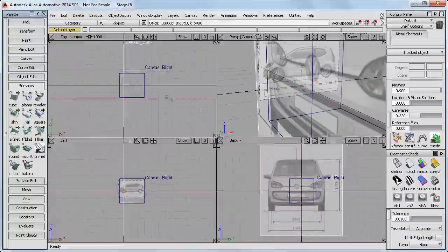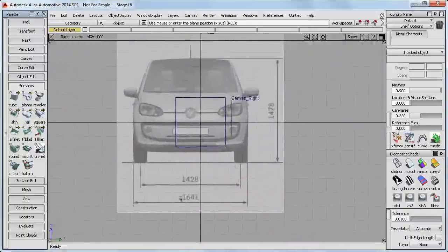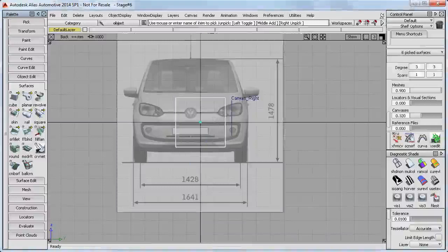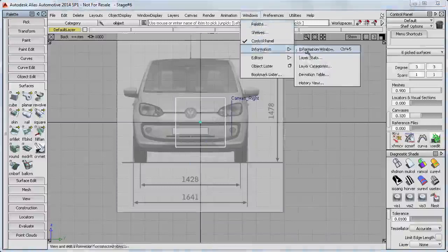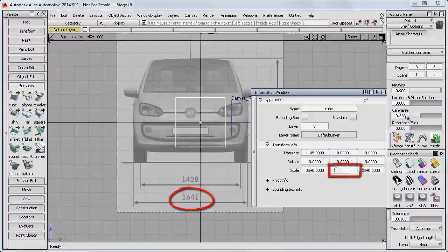Again, it comes in at a random scale, but I've got the overall dimensions here, so I can refine my reference cube to having the right size. And I could have used any reference geometry, cylinders for the wheels, for example, lines, just anything that's a true size.